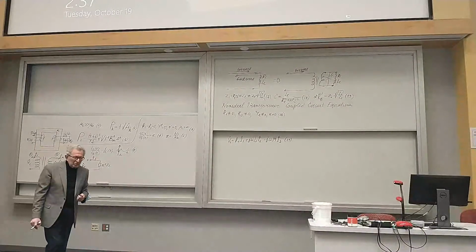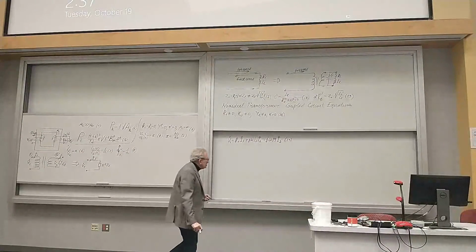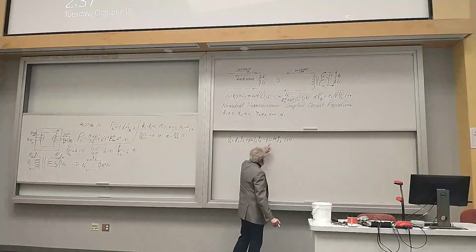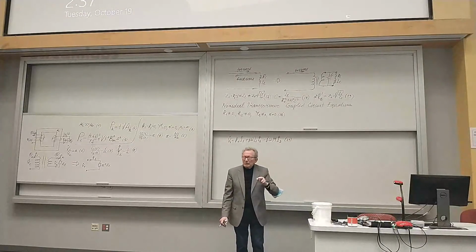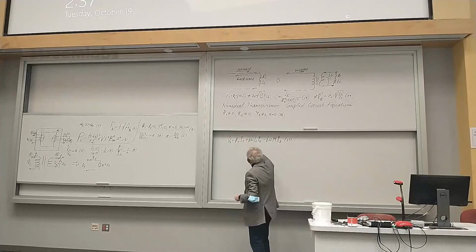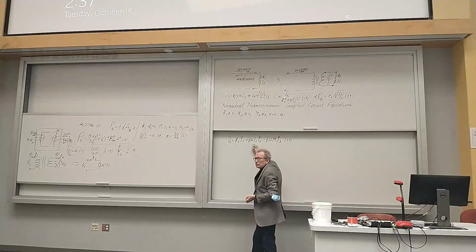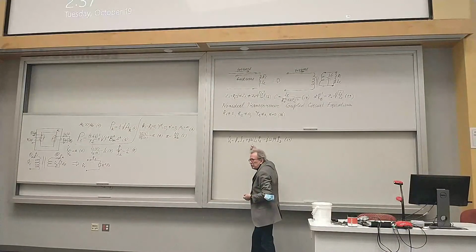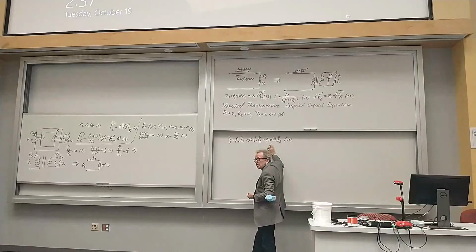So you can see that in this case, we have three components of the voltages of distinct nature. One is a drop of the voltage due to the resistance, which is assumed non-zero. Another is a drop of the voltage due to the inductance of the primary winding, and another is due to mutual coupling between the primary and secondary winding, which is described by mutual inductance.